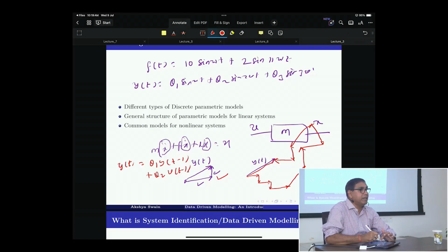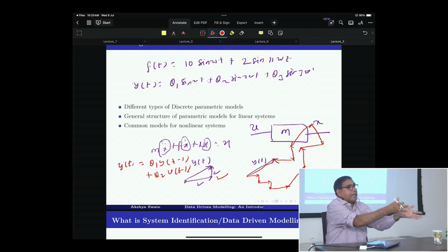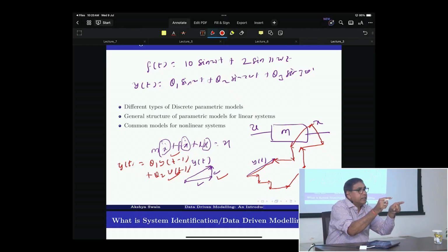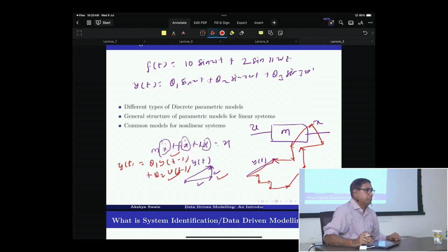I substitute here, then this equation will change, and you identify that equation. So you identify the entire system, but the system actually has a y term and a u term, and by that feedback, this y is getting replaced by k into u. So the identification is lost. The system has a y term, but because you are doing some manipulation here, things are changing. I'm giving the example, it is not clear yet, I'll tell you one thing here.